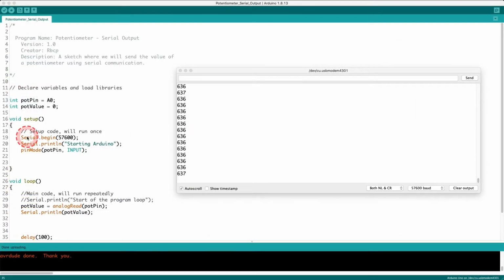In order for the Node-RED program to work properly, you need to ensure you have completed the previous video and uploaded the sketch to the Arduino. The sketch reads the value of a potentiometer and prints it to the serial monitor. Ensure that the Arduino is plugged in and working. Also, make sure the Arduino IDE is closed when you complete this video. Only one application can connect and read the Arduino serial at once.